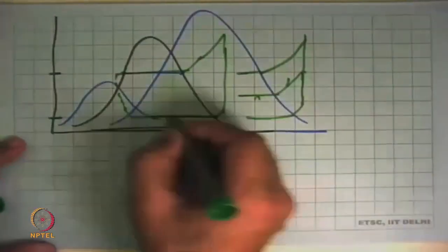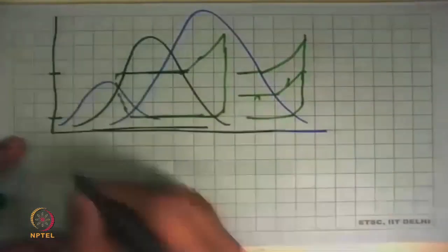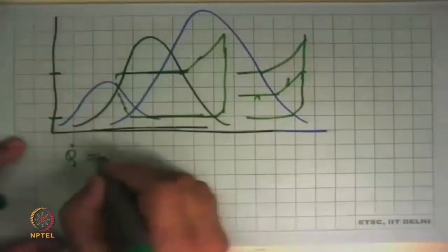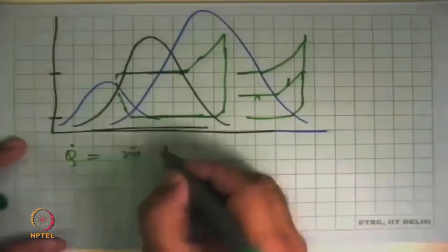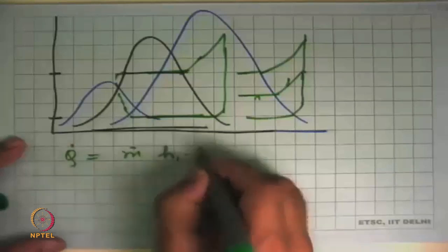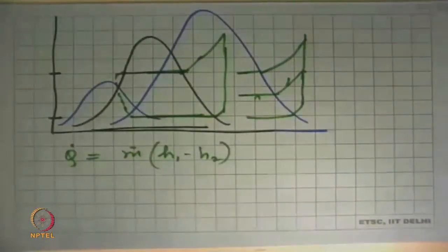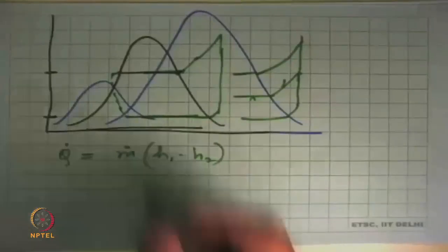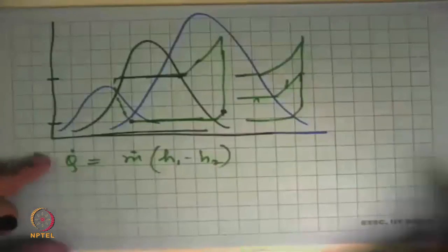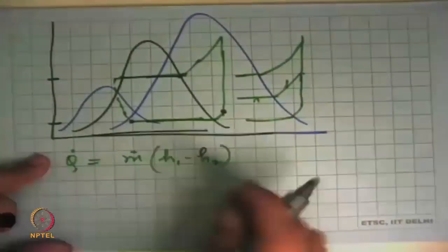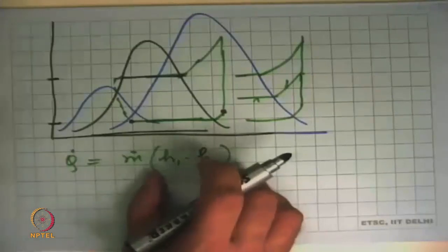Now what is happening is, you look at these two states, and you say, first of all, my cooling rate will be m dot times the change in the specific enthalpy, say h1 minus h2 or whatever that may be. Now, do I get a sufficiently large delta h from this state to this state? And if you see that problem in the assignment, you'll find that for some refrigerants, this value is a few hundred. For water, this value is a couple of thousand.